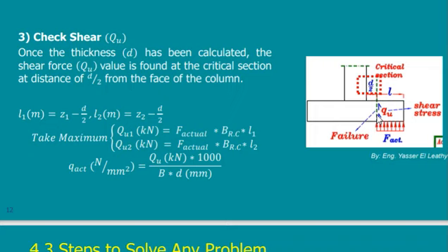If I have something and I am pushing on top of it, you cannot shear it. You can shear it only if you are pushing away and there is a cantilever part. But below what you are pushing, you cannot shear. So this is the same idea. This column prevents you from shearing below it till a certain distance. Take it d by 2.